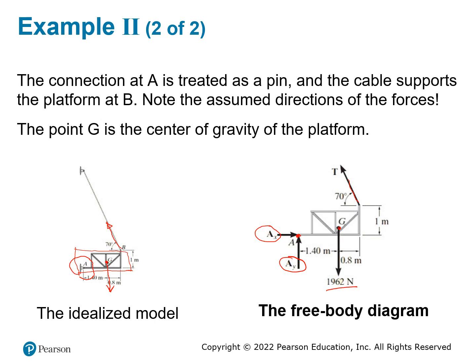And once you have the free body diagram, you're going to use the same idea: try to find the summation of Fx, the summation of Fy, and the summation of moments, and you're going to choose the reference point. I'm going to choose this point as well. I'm going to put A here. That will be a lot easier for the calculation. For this one here, it is not horizontal or vertical, so you have to decompose it into Tx and Ty, so you can do this calculation more easily. Okay, so that's how you solve the second problem here.